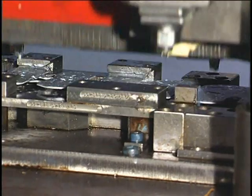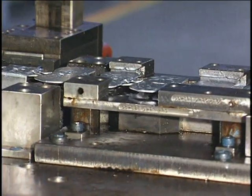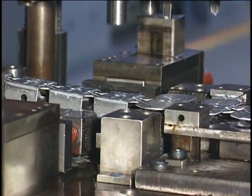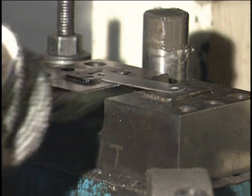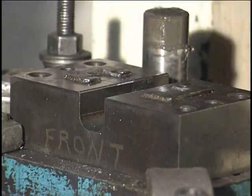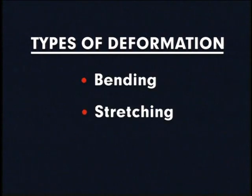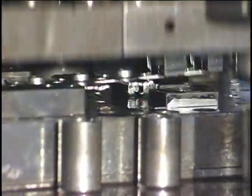The main manufacturing requirement for most sheet metal applications is good formability. This is the sheet metal's ability to deform into intricate shapes without defects in the finished part. In all sheet metal forming operations, one or more types of deformation are involved, including bending, stretching, and/or drawing. Part shape largely determines the relative severity of the sheet metal's formability, especially where drawing and stretching occur.